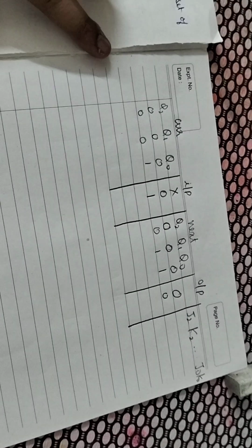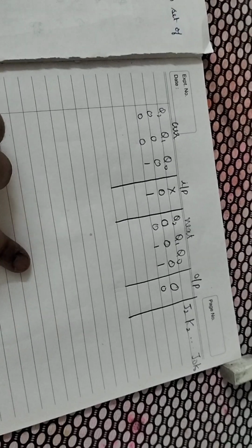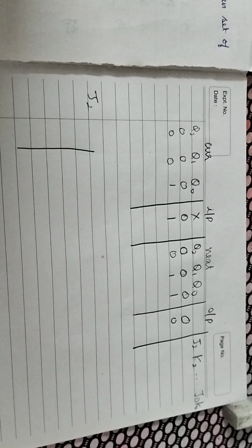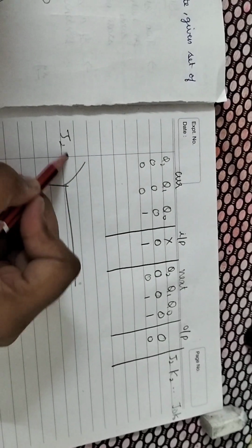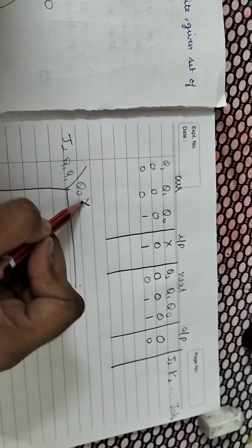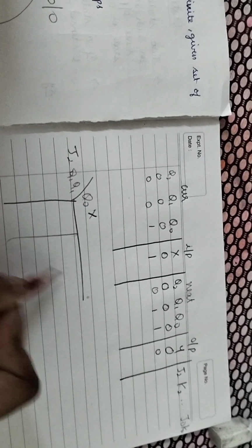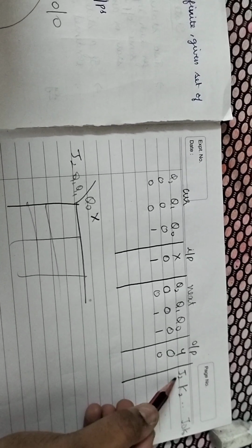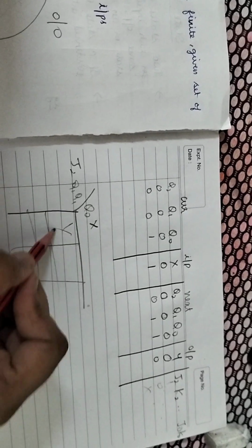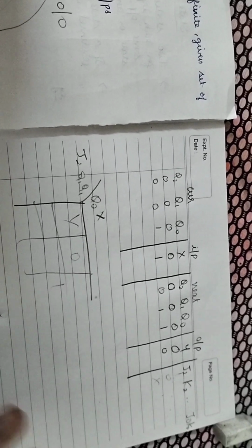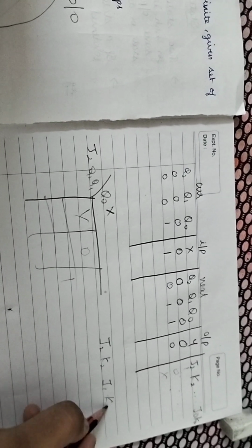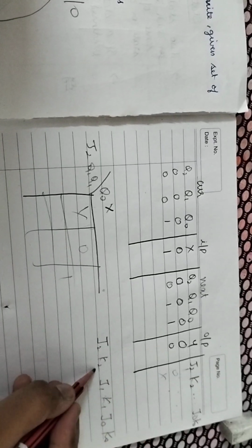And then once that is done, you will draw your K-map. Let's say you're drawing for J2, the K-map will take the 3 current states and the input as its variables. So you will have Q2, Q1, Q0, X. So you will draw the K-maps. Of course, you will fill in these using the excitation table. You will get ones, zeros and don't cares. So you will put them in and you will do the grouping as usual. You will find out expressions for J2, K2, J1, K1, J0, K0 and for the output Y.